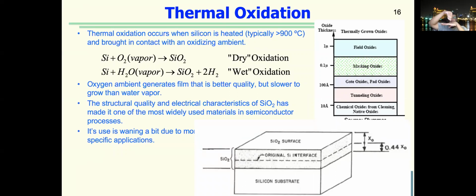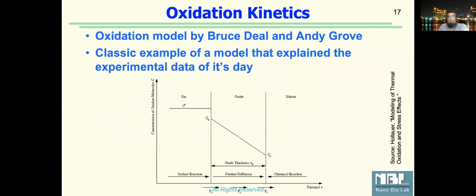When oxidation starts, there's just silicon; it would consume silicon and turn it into silicon dioxide, so you have a quartz kind of network. But now the next oxygen has to squeeze through, to diffuse through, to get to the next silicon molecule. So the thickness goes up and the reaction goes down. How do we understand that?